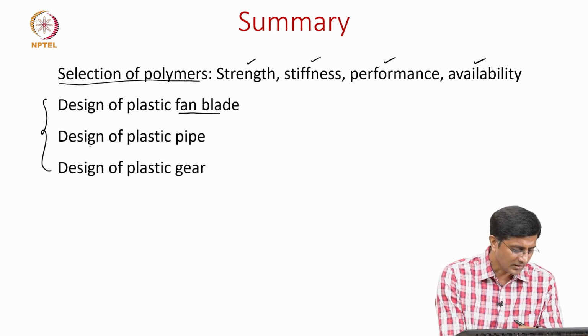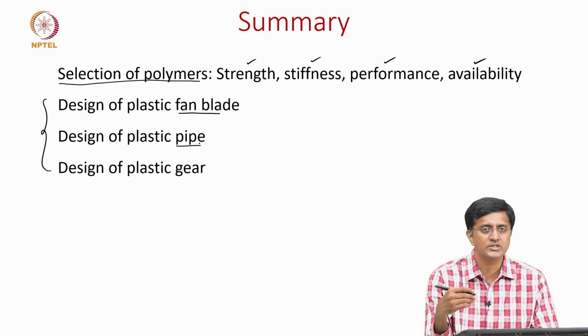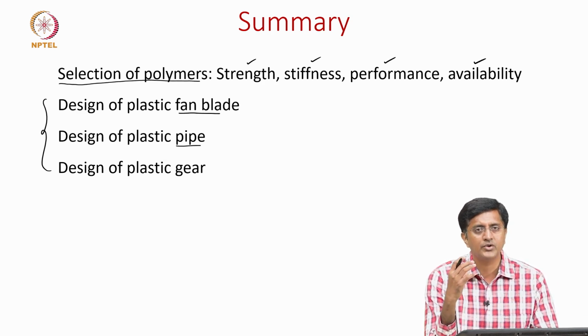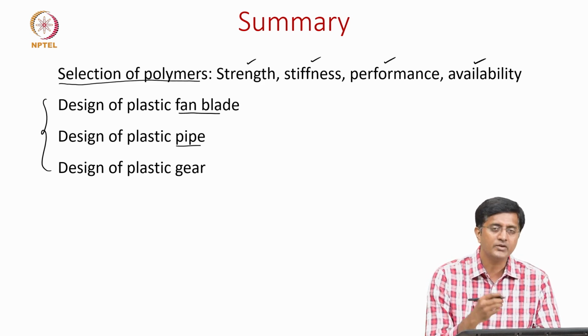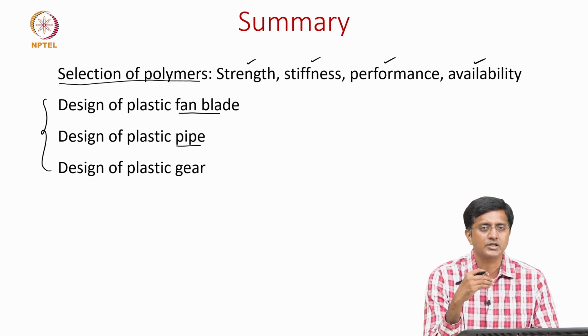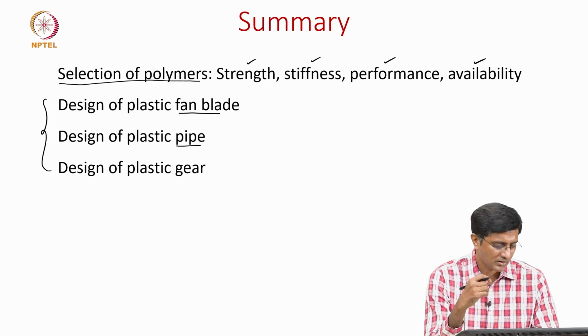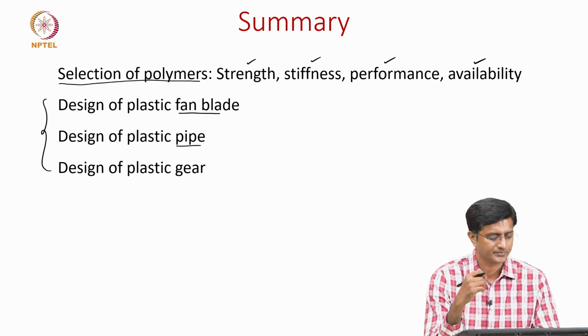Later we moved on to these plastic pipes, which are made of either PVC or HDPE, saying that again we need to consider the hoop stresses as well as look into the swelling occurring in these pipes because of either water absorption or the constant stresses applied. There again we said isochronous stress strain curves can be used in terms of pipe design.